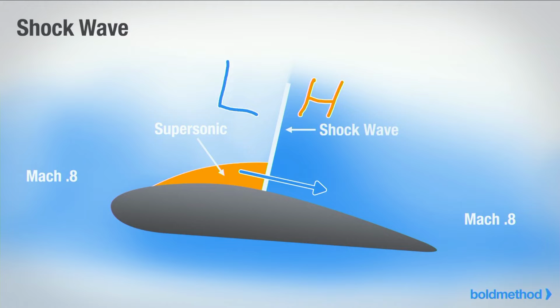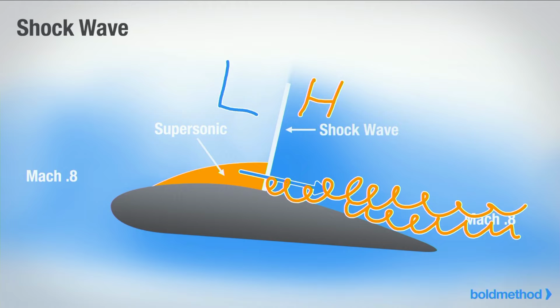Okay, so essentially, when we start taking energy away from the air, when it's moving across an adverse pressure gradient and it's losing that energy, it can separate from the wing and it can cause a stall. Okay, so now we look at a shock wave. And the problem here is this is like 1,000 times worse than what you would normally get off of just a normal pressure gradient, because the change is so aggressive as it crosses the shock wave. It's so drastic that it can quickly cause airflow to separate. And so, boom, all of the airflow here now separates off.